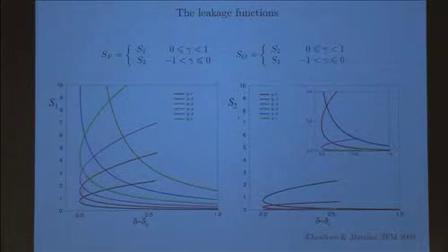This shows you that when delta is bigger than delta critical, you also have a significant amount of leakage of fuel and oxidizer through the flame. I gave you a description of that before, but now we were able to compute them. So, for example, for gamma positive, S1 represents the fuel leakage, and you see different values of gamma. And for gamma equal to 0, this represents the oxidizer leakage.